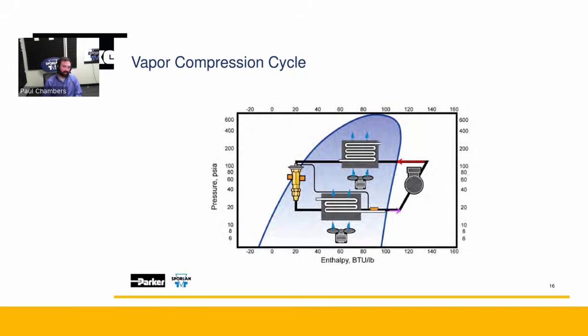And the other error that I noticed while making this, and hopefully someone else could catch, is that if you're using a TEV, or TXV as some call it, like I said, you can use those to control to a superheat. It's always creating a pressure drop to make sure you get enough boiling to get to superheat. Well, that bulb of the valve would need to be measuring superheat to say, well, we're going to measure at that pressure-temperature relationship to create superheat.